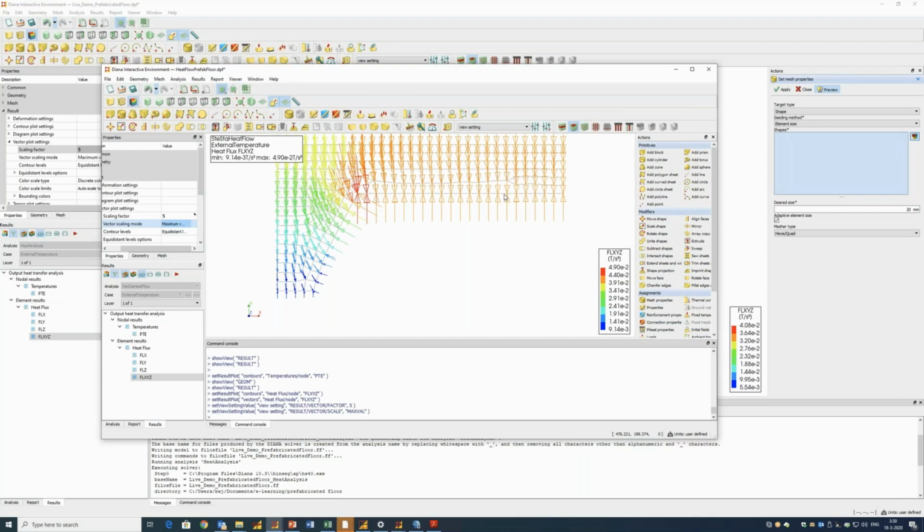So this is it for the live demo of today. We have built a model, relatively simple 2D, on which we have assigned heat flow property by means of conductivity parameter. We have defined mixed boundary condition, so using flow boundary interface, and we have performed a steady state analysis. And we could see the temperature contour plot and the fluxes resulting from this analysis. And we could also see the impact of this insulation layer on this model.